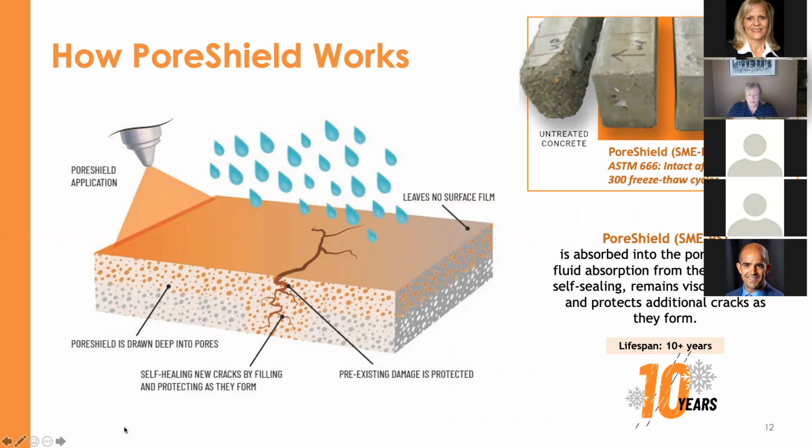So how does it work? Well, let me tell you how it doesn't work first. I think we're all really familiar with coatings that go onto a surface or things that are called penetrating sealers, things like siloxanes and silanes. They do provide initial protection by going across the surface of concrete. There's a chemical reaction that occurs, so that cures, and it prevents moisture ions from penetrating concrete. But it's a short-term protection. They're often referred to as sacrificial coatings, and that is even true for engineering thermoplastics like epoxy coatings. Once that coating has either been eroded or damaged, water and salt can get into the surface.